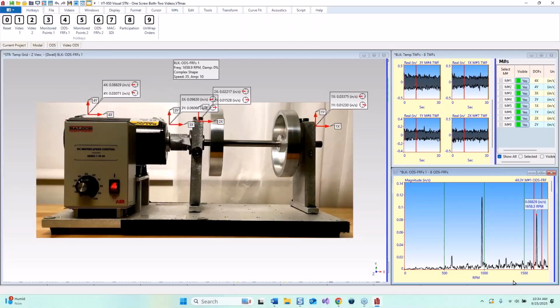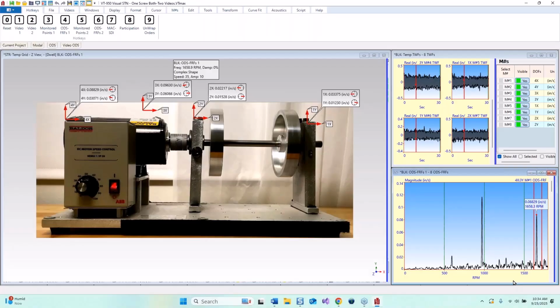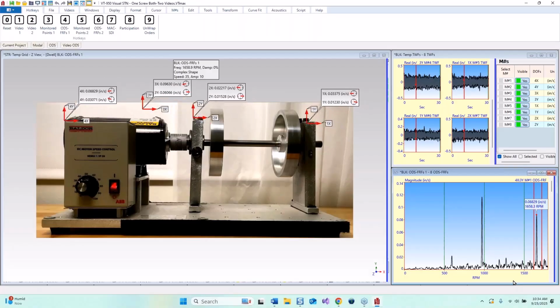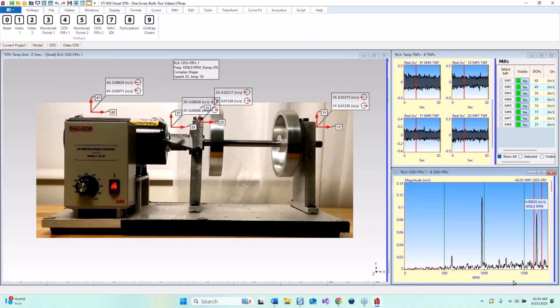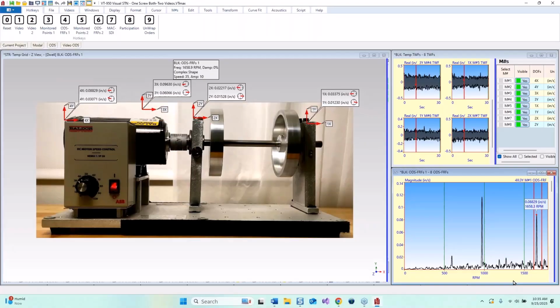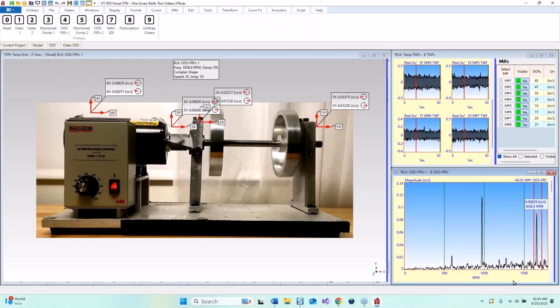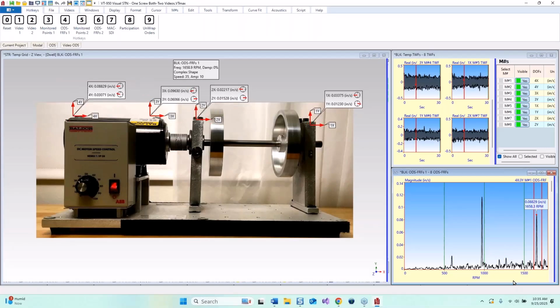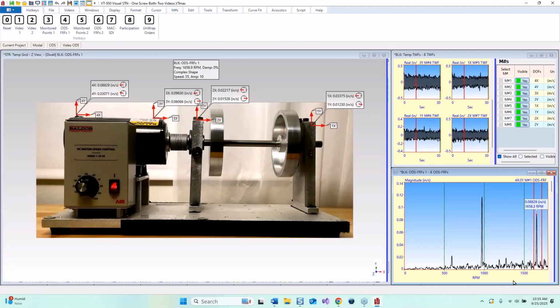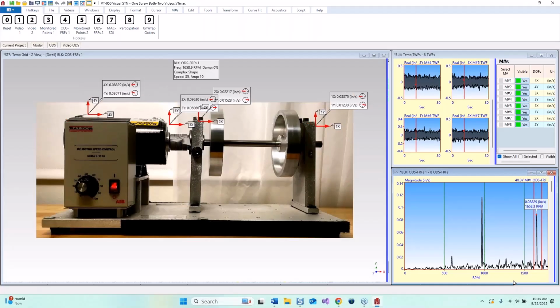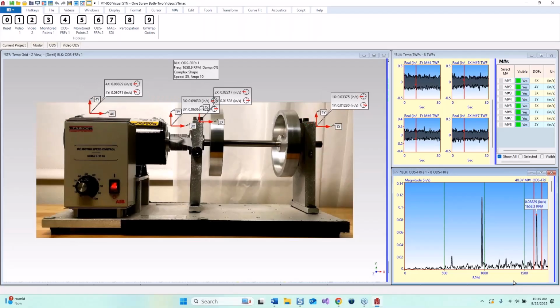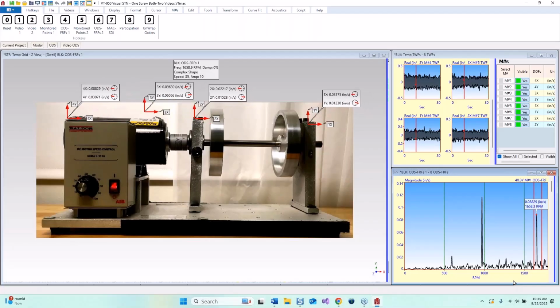So just thinking out loud here, the data was recorded at 60 frames a second times 60. That means the sample rate of this data was 3600 RPM. And then in the frequency domain, one of the rules of the FFT is that the spectrum, any frequency data, is 1/2 of the sample rate. So the maximum frequency, what we call F max of the ODS FRFs, is 1800 RPM.